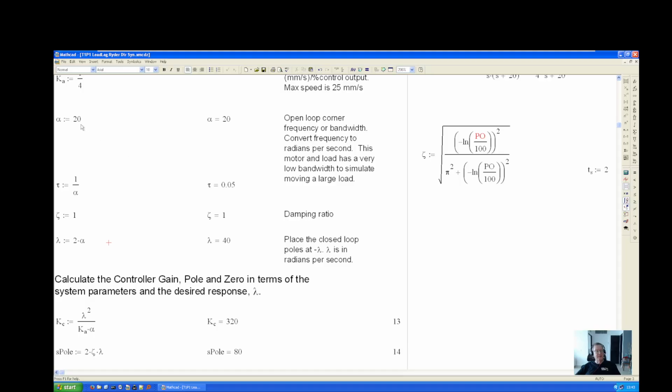This is the corner frequency. I just inverted this for general information, but if you take 4 time constants, then you get a rise time of about 0.2 seconds. That isn't really achievable in this system unless you're making a very small step, because the controller output will saturate.